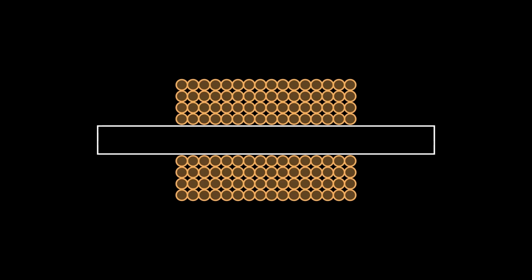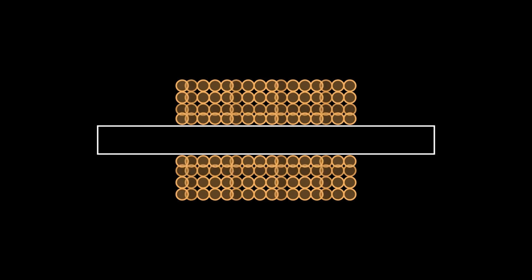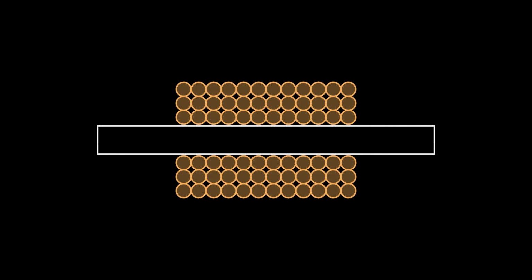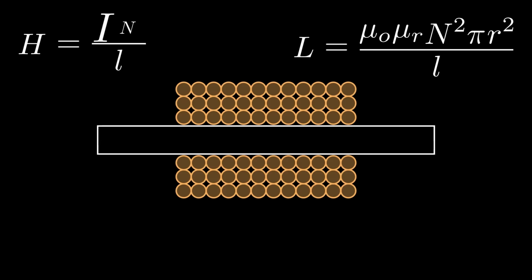Next, we'll keep the exact same coil radius and length as the baseline, but change the wire diameter to 1 millimeter. This ends up giving us an arrangement of 5 layers by 56 turns. In doing this, we will have a decreased resistance, meaning an increase in maximum current, but fewer turns to contribute to producing the magnetic field. We also expect to see a reduced inductance due to the fewer turns, allowing a faster current ramp.